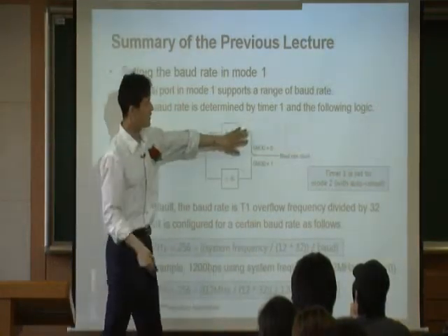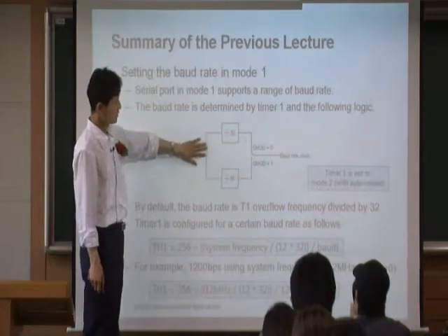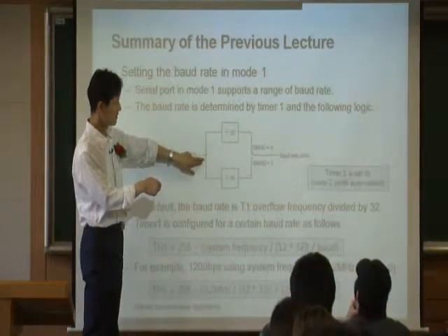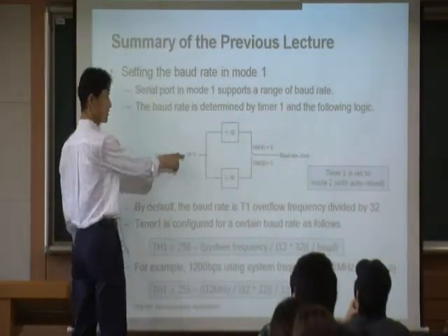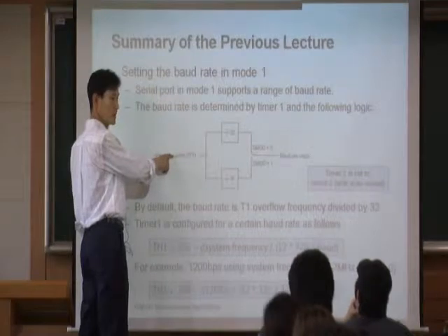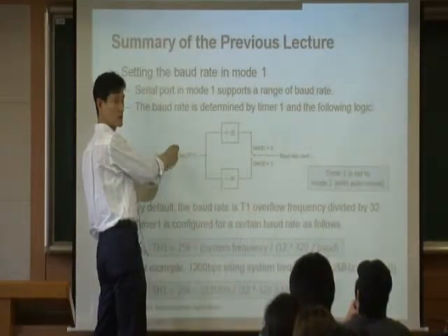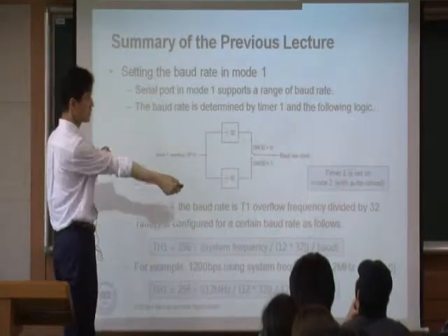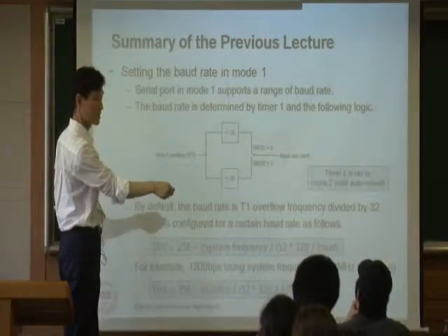So in order to get the 800 microsecond here, at the input of this block, how much delay do you need for every overflow? 800 divided by 32, right? So that's what you need. Because you do the divide by 32, you have a slower clock right here.